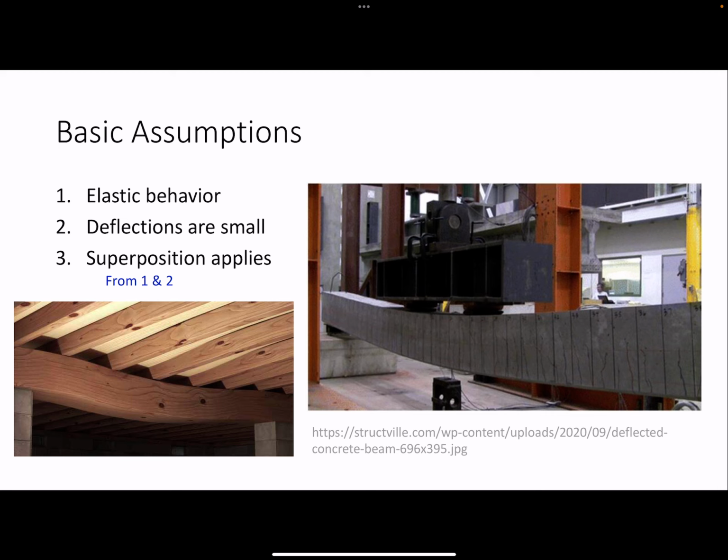So this beam could potentially still be elastic. If you remove that load, it may return to its original position. I don't really know exactly. It depends on whether the steel has yielded inside, but it doesn't appear externally to have any definite signs of permanent failure or permanent yield.